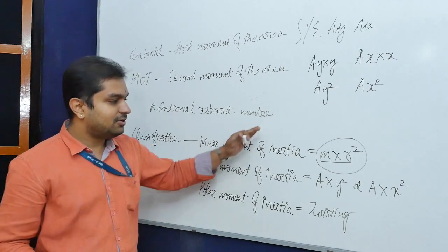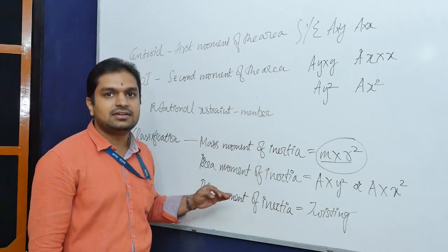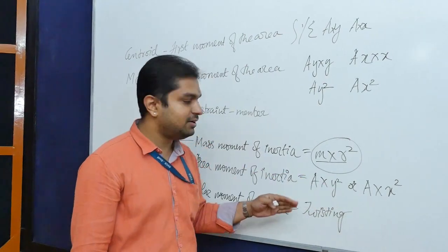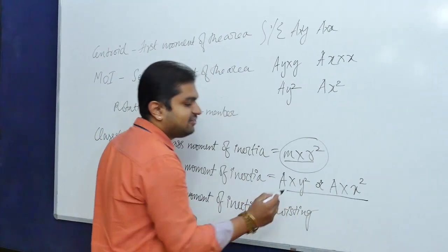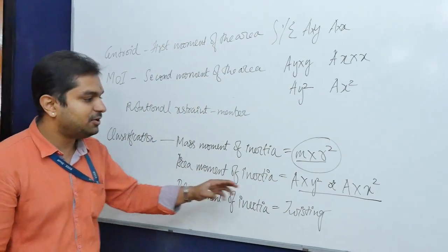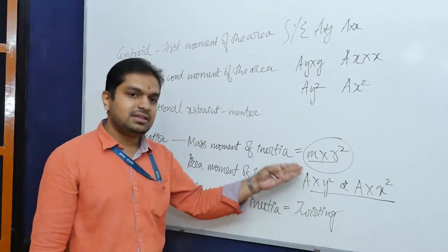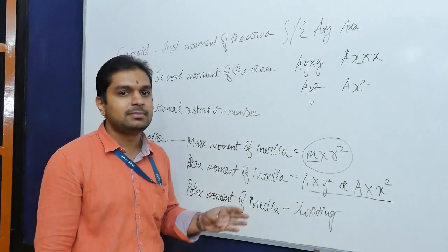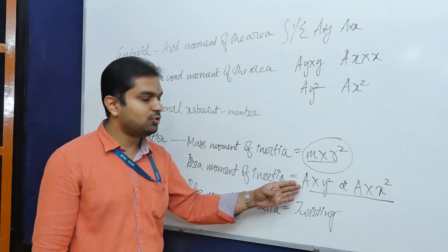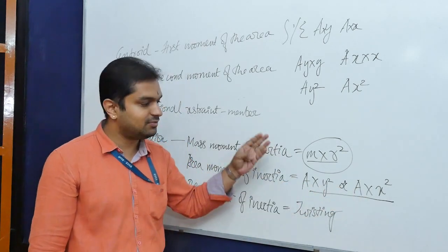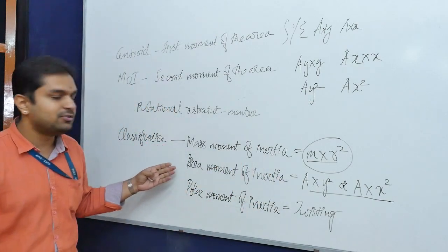So in line with all these basic classifications, since we spoke of the centroid in the previous unit, in relation to the syllabus we will be discussing only the area moment of inertia. Area moment of inertia is where you find the corresponding centroidal distances and the area of the individual areas of a given composite shape, where you divide it into areas of known dimensions and properties along with the centroidal distances from the reference axis. You will then be able to compute the area moment of inertia.